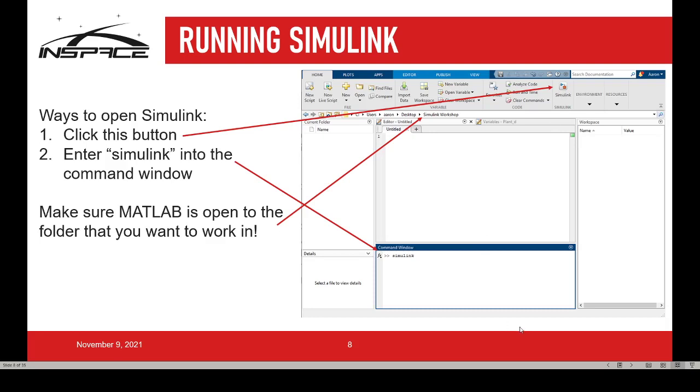Or you can just enter Simulink into the command window. I like to do that because it makes me feel cool, but it's more button presses. You also want to make sure that every time you're editing a MATLAB file, a Simulink file, or anything related to MATLAB, that you have it open to the folder that you want to work in. Here I had a folder called Simulink Workshop that I made sure it was all done in, and that way I could make sure whenever I was saving stuff from Simulink or to Simulink to the MATLAB workspace, I knew it was all going to be going to the same place.